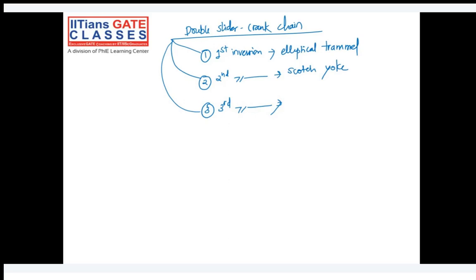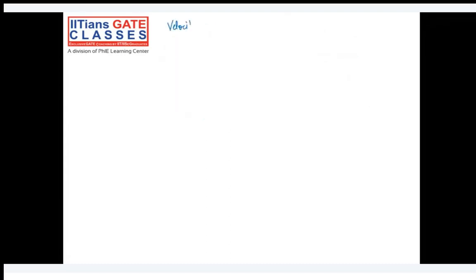Okay, so this is what mainly we have studied in this chapter. Apart from this, if I come to the velocity and acceleration topic, we have studied how to draw the velocity diagram, how to calculate the velocity of, let's say, a turning pair, a sliding pair, a turn slide pair, etc. So velocity for a turning pair is r times omega, and the acceleration will have two components: a centripetal acceleration r omega square, which is towards the center, and r alpha, the tangential acceleration.